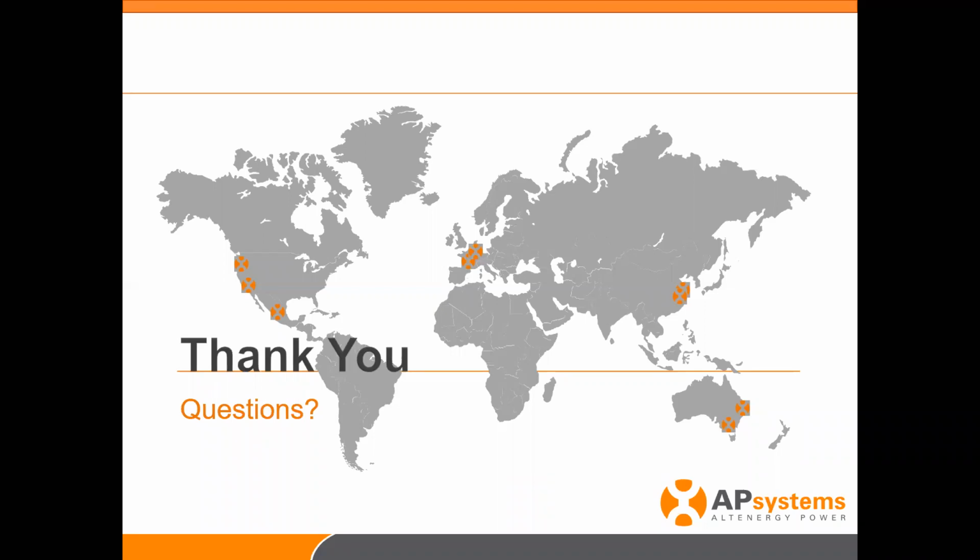Some module manufacturers publish it, some don't. So I would encourage anyone who's looking at modules and right sizing their system for microinverters to size it to the PTC, or the practical side of it. So basically what you would expect to see. Like I said, most module manufacturers have that information. Some publish, some don't. But there's also a great resource online.